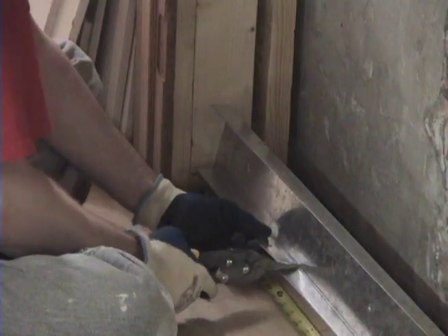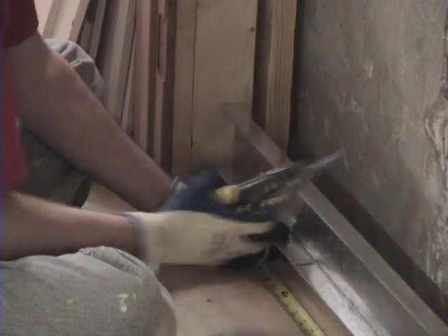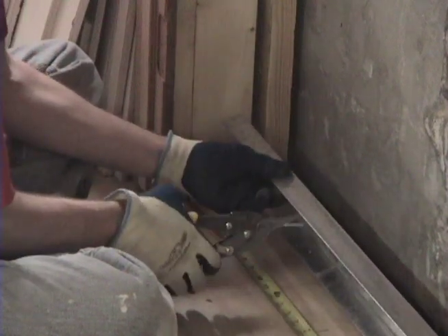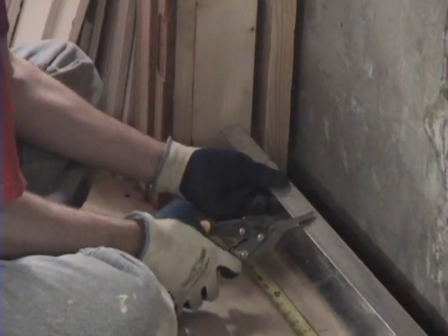Steel studs are an alternative to wood. I used both in my construction. RC doesn't improve steel stud isolation because steel studs have inherent resiliency as they support the drywall. Generally, steel studs isolate better than wood, so the decision is completely up to you. Like wood, you start with a base plate. You cut the length with tin snips and then bend it up to make a right angle.